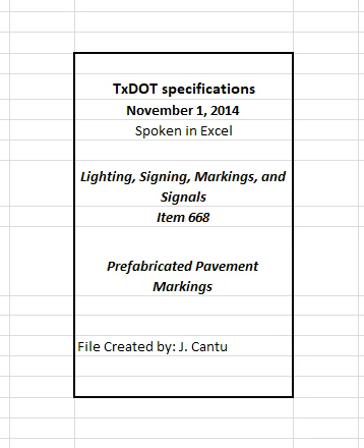Prepare surfaces further after cleaning by sealing or priming as recommended by the pavement marking material manufacturer or as directed. Use adhesive, when required, of the type and quality recommended by the pavement marking material manufacturer. Do not clean concrete pavement surfaces by grinding. 3.6 Performance requirements.